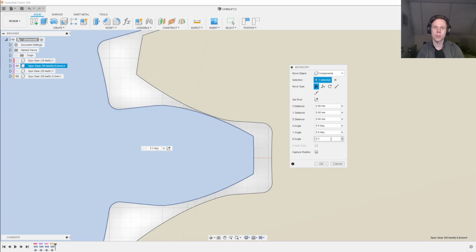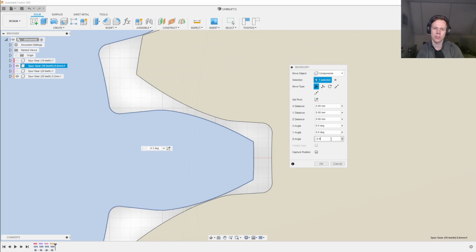So let's say the gears are in a position like this and I want to reverse direction. Well, the gear will start moving in the other direction, but its mating gear won't start moving yet because it's not yet in contact with the tooth. And only once we reach about this angle, 0.4 degrees, will the other gear actually be touched and start moving. This notion is referred to as backlash: you can move one gear in the reverse direction and it takes a while before it acts on the other gear.